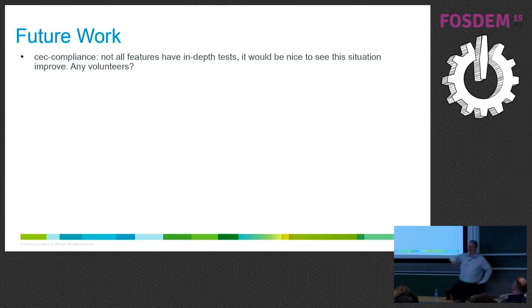The CEC standard, by the way, is part of the HDMI specification. The HDMI 1.3 is freely available. 1.4, use Google, let me put it that way. 2.0 or 2.1 are not available, but 1.3 gives you about 90% of everything you need to know. What they did in later versions was mostly tighten the thumb screws a bit on vendors, to ensure a bit better compliance.